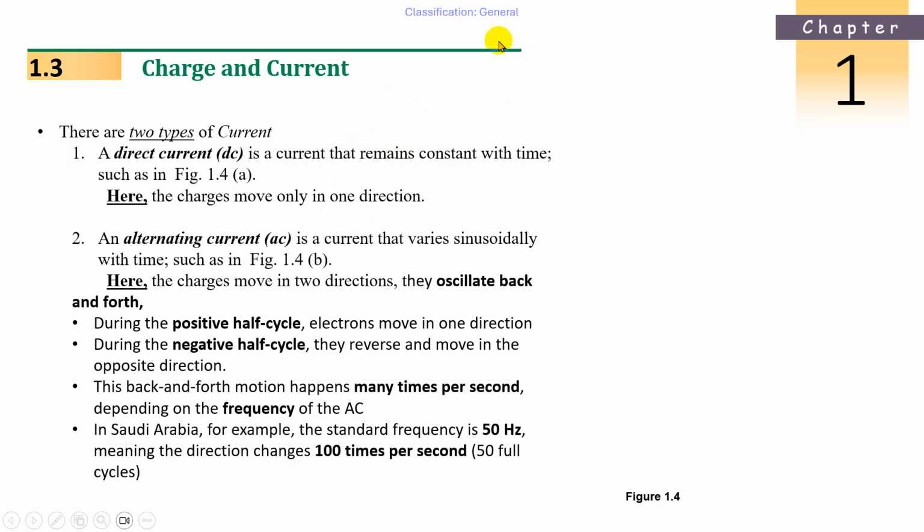So can you observe that? Off, on, off, on, off, on. No, because our eye has a limitation. We can only see about 10 times. In 1 second, if it is on and off 10 times, you can see that, but not more than that. It is 60 times, so it looks like a constant. It is AC, but it looks constant only because our eye can't see. If we connect a device, an oscilloscope, there you can see 0 to maximum, to 0, to negative maximum, to 0.